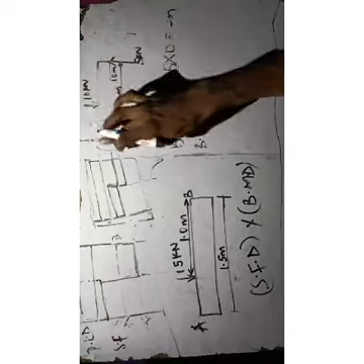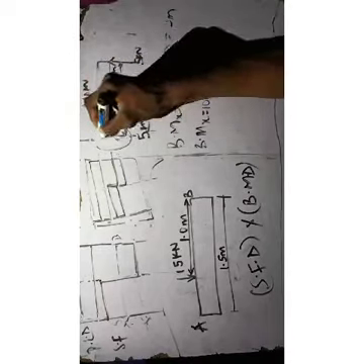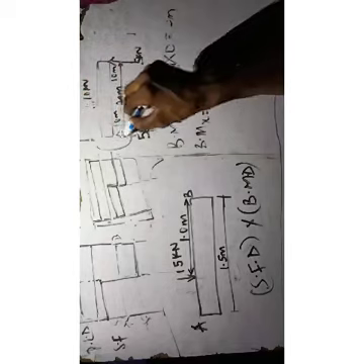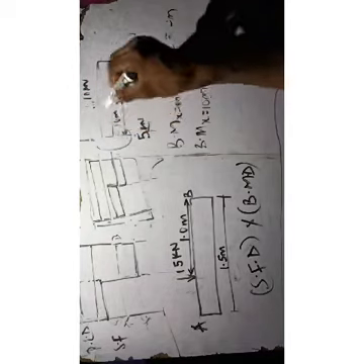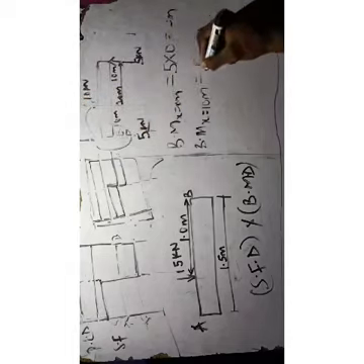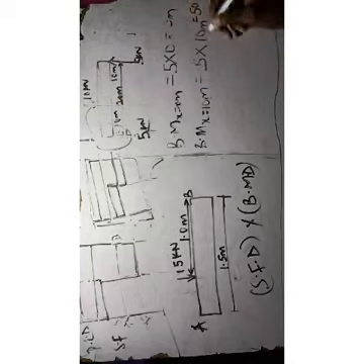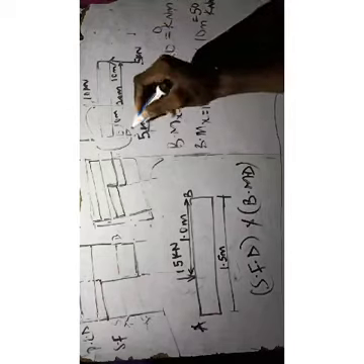Okay, so the bending moment when x equals 10 meter will be force times distance. So this will not be at point A now. Now the bending moment when x equals 10 is here. The force is acting up, right? The distance it is covering is 10, right? The force is 5. That will be 5 times 10 meter, and that will be equal to 50. Don't forget your bending moment is in kilonewton meter. That will be 0 kilonewton meter here, and this will be 50 kilonewton meter. That is the force acting times the total distance covered, which is 10.